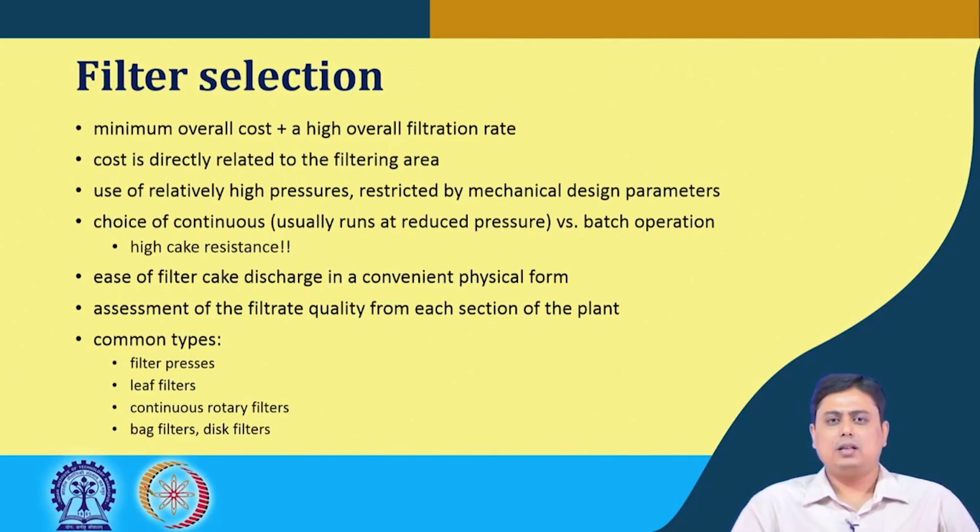In such a case this batch mode operation can be helpful, because once the cake is deposited, we can take out that cake, separate it, and again start the operation. So instead of continuous operation, in certain cases this batch mode of operation is useful.